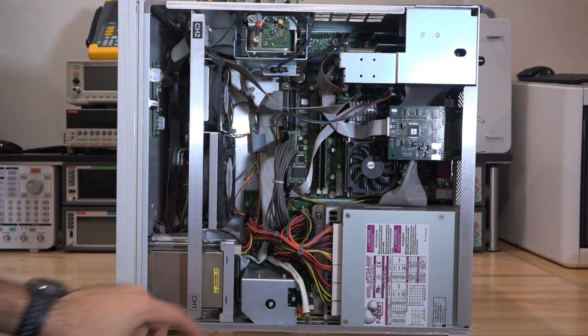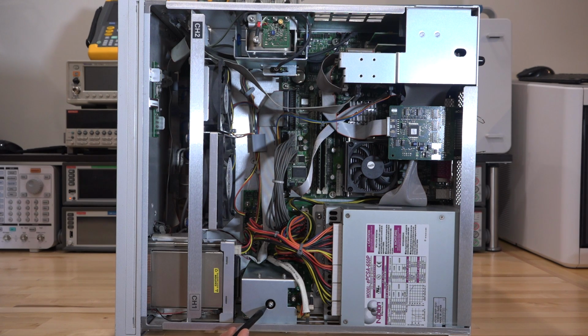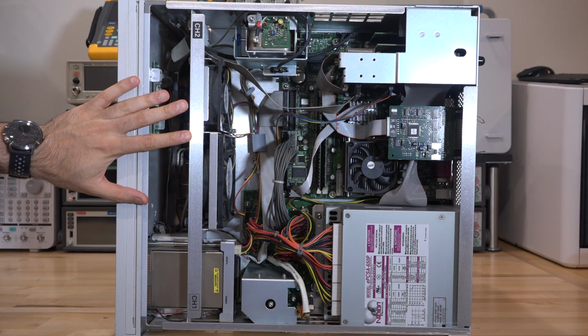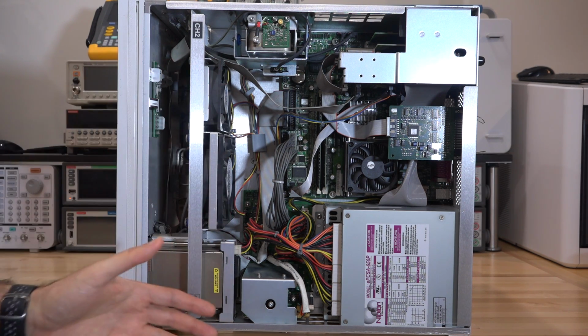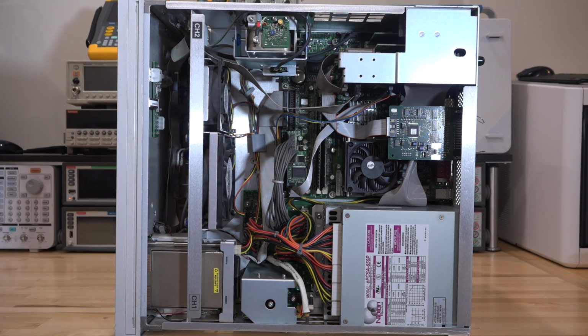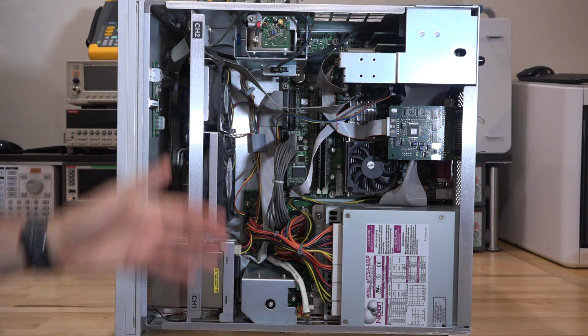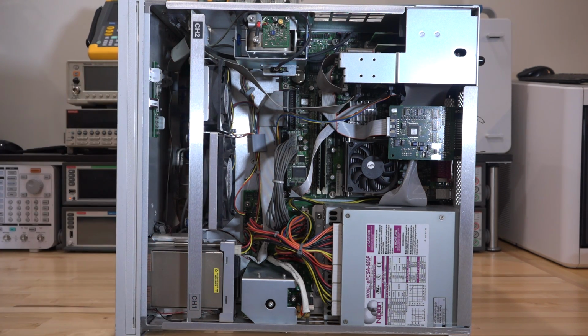And both of these are on shock absorbers, you can see, and even though this is on its side, I can move the entire structure around because it is on rubber feet, allowing it to absorb any vibration. Normally you don't have to go through this much trouble if you're making a spectrum analyzer or a synthesizer, but when you want to measure phase noise down to 1 hertz offset, you don't want any vibration feeding into the core of your PLL, because that's going to throw everything off. So you want to be as quiet as possible. This is the reason why these are such large, very high quality oven-controlled crystal oscillators. I don't know what the Allan variance of these is, but I'm assuming that it's very good.